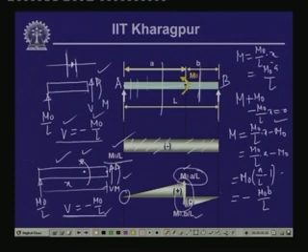On the left hand side we have got a positive M0 A by L, on the right hand side we have got negative M0 B by L, and basically the variation is something like this. So, here it is going from 0 to this value, then it is varying like this, and from this to 0 value. Now, this particular distance being very small, we approximate that as a straight line instead of that inclined line, and this is what is reflected in this particular diagram.